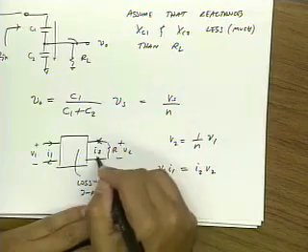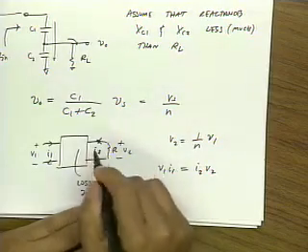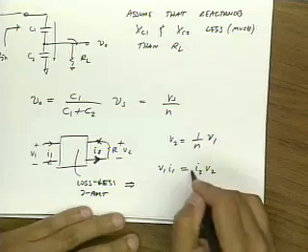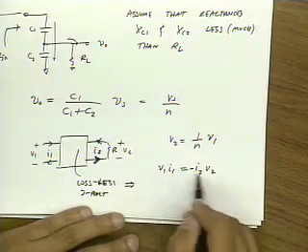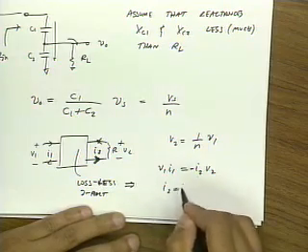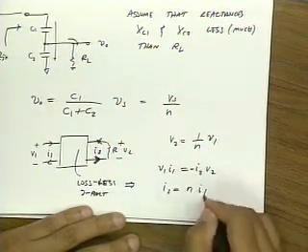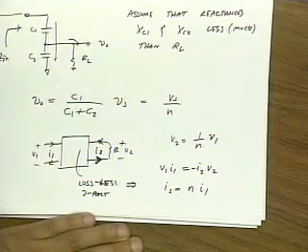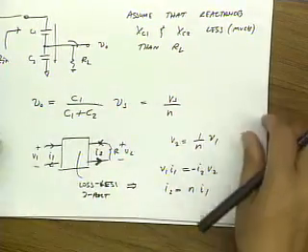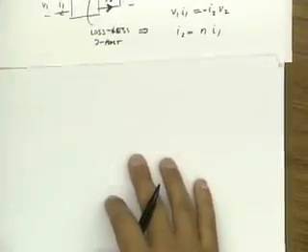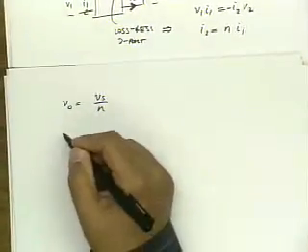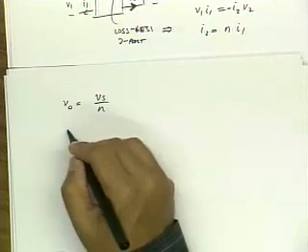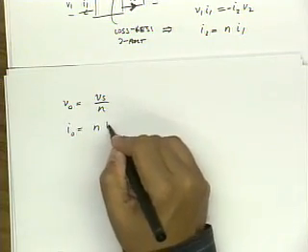Actually, I2 is defined in this direction. It's the current going into the 2 ports. So whatever power I put in should equal minus the power I take out, because it's lossless. That means if there's voltage gain, then the current gain should be the opposite of the voltage gain, right? So for our voltage divider, you might expect that because the output voltage is N times smaller than the input voltage, then the output current should be N times larger.